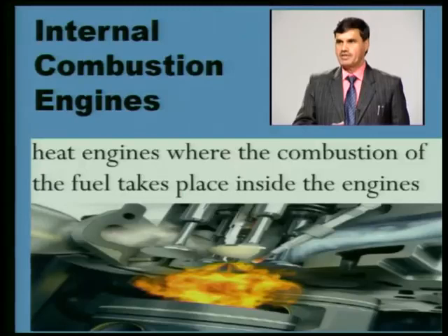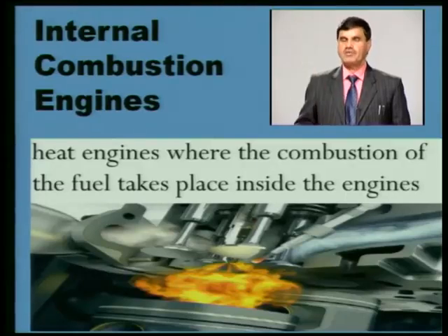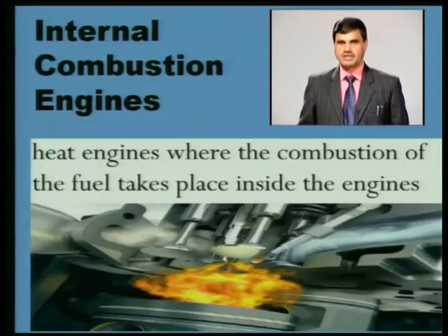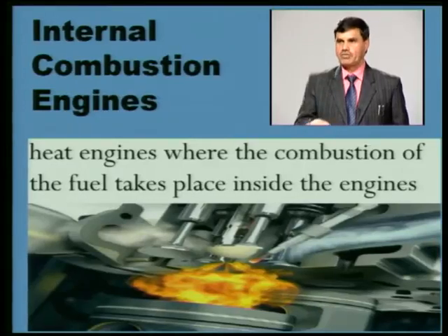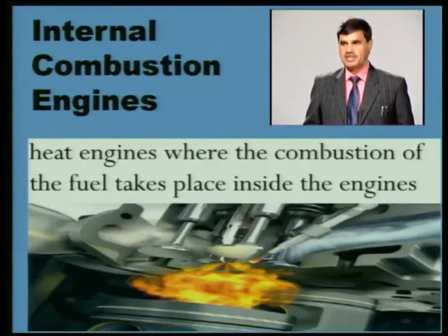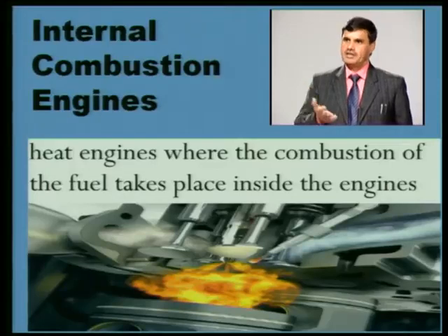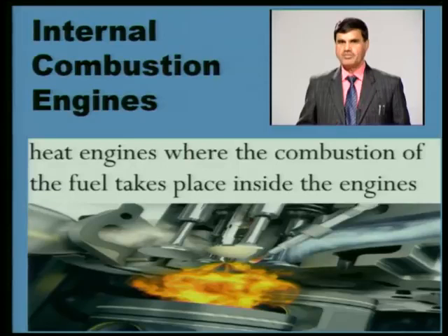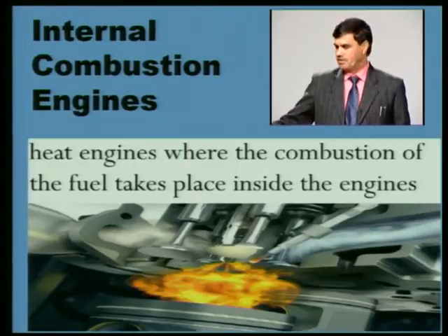When the power stroke is completed, the movement of the piston in the downward direction is completed, and the piston comes back in the upward direction. Like this, continuous piston movement is possible inside the cylinder, meaning the piston is reciprocating from the upper part to the lower part and from the lower side to the upper side. The reciprocating movement of this piston is converted into rotary movement of the crankshaft, and that is finally responsible for giving the work output.